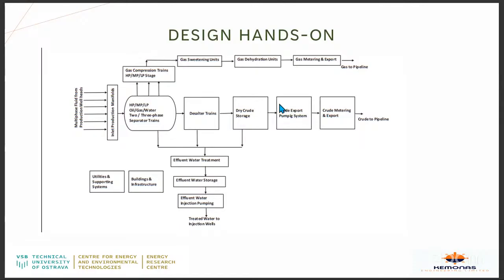So now that I just mentioned corrosion, I have to remember that corrosion engineers are also important in this industry because they have a role during the development stage, during the design stage. They advise on what type of equipment to use, or whether carbon steel, and also the rating of the equipment, the thickness of the equipment, and they will decide the lifespan of the equipment. For example, for vessels and pipelines, they have different lifespans.